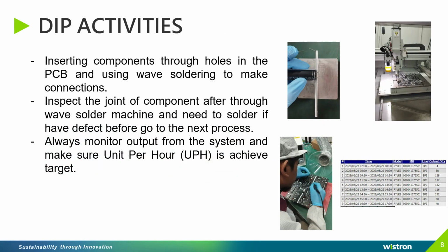So what I do in the DIP section, first of all, I got to learn and was exposed to inserting components through the holes in the PCB and using wave soldering to make the connection. And in the DIP section I also inspect the joints of components after they go through the wave solder machine, and need to solder if there is a defect before going to the next process. And I also always monitor the output from the system and make sure units per hour achieve the target.